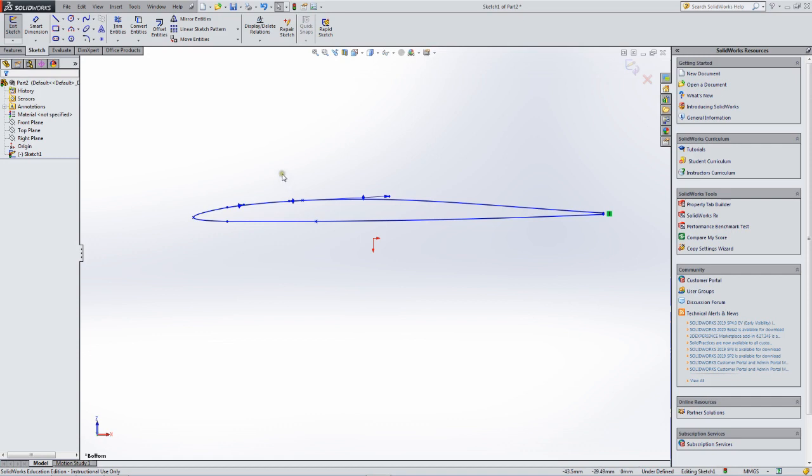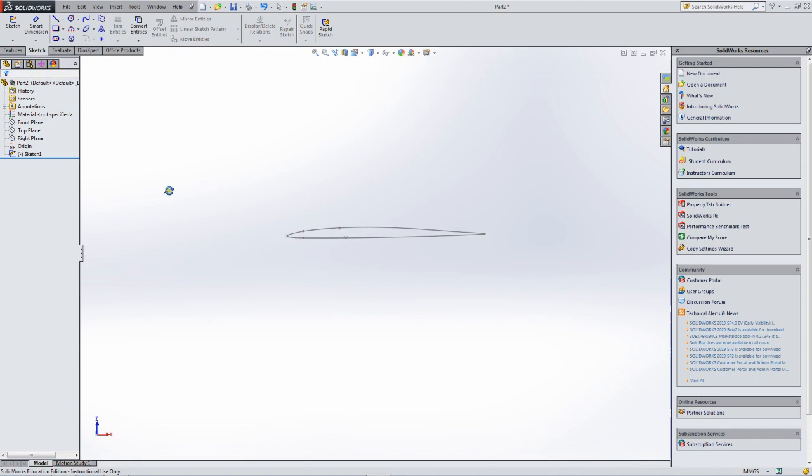As I said, it's quite a thin airfoil. Once again, checking, I've got X in the positive direction from left to right. I've got Z positive up, and Y is away from me, out the right wing. So this is the root chord. Then I'll go out the right wing and make a tip chord, and then I'll loft the wing. I'll hit exit sketch here because I'm happy with this drawing, and then I need to define another plane out at the wingtip to draw my wingtip chord and then do the loft.